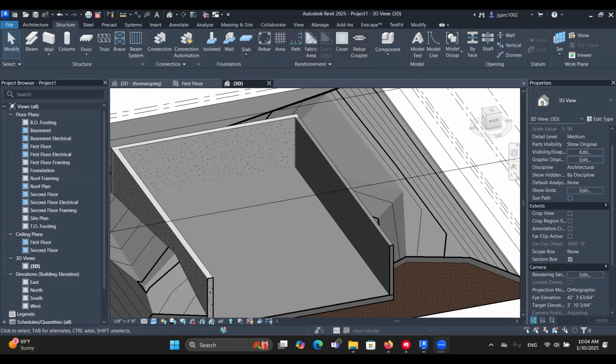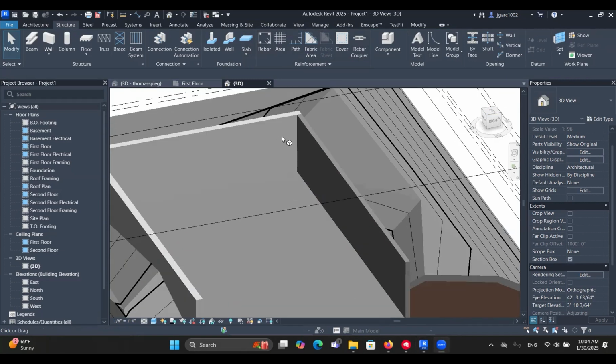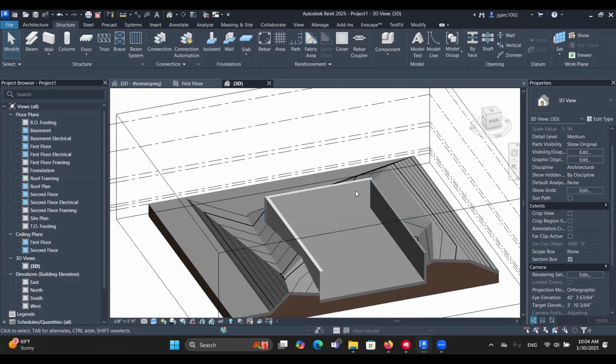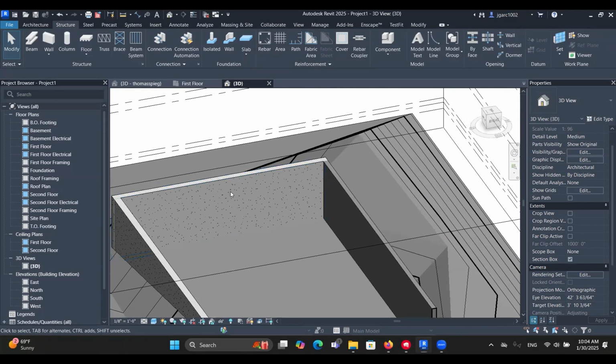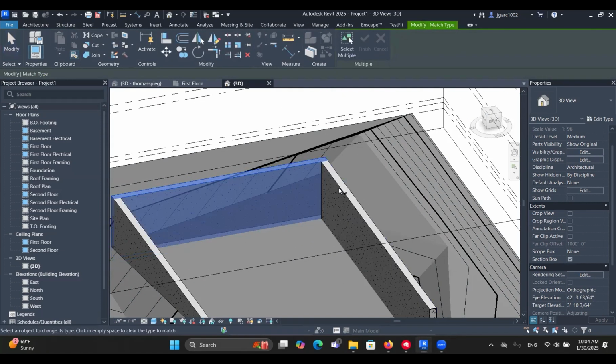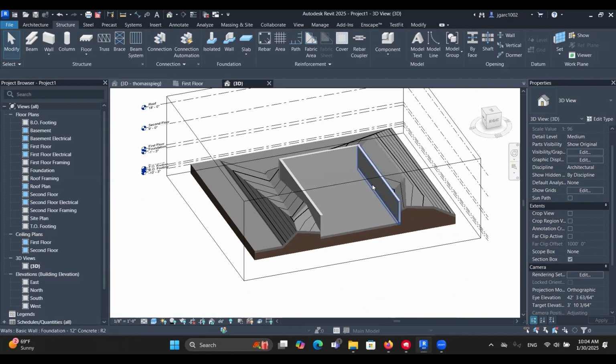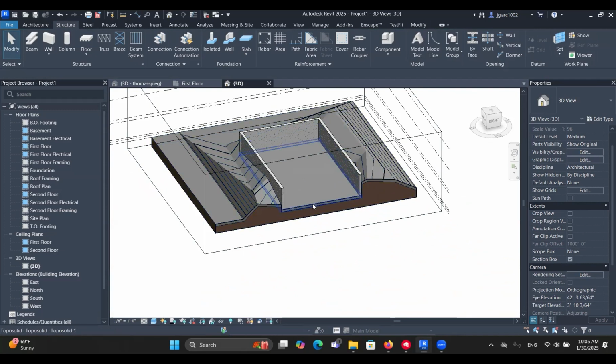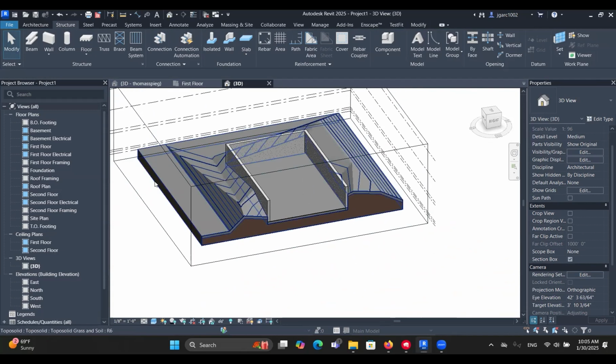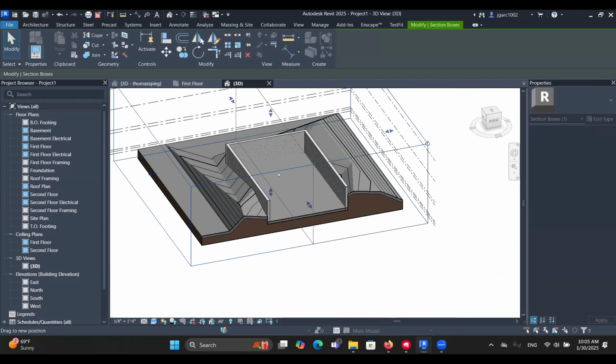And this is going to work for annotations, wall types, anything really that you want to match, that is the same kind of element in the software. You can match all the properties that this element has. So say you wanted to match the properties from the masonry wall that you already have. So MA, you select your reference and then you click here, boom, you have that already selected. So it's really cool because you get to work faster. Let's go over editing a wall.